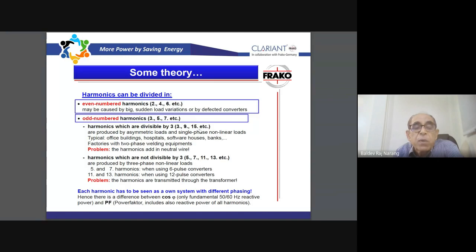They all create similar problems, and we have to take care of all of them. But maybe the means are different. Zero sequence currents add together and flow through the neutral, so we have an unbalanced current in the neutral. We also have harmonic current in the neutral for single phase loads, like hospitals, some commercial buildings, or even IT buildings where single phase loads are there. So there zero sequence harmonic is a challenge, and the neutral is taking the burden of all these harmonics.